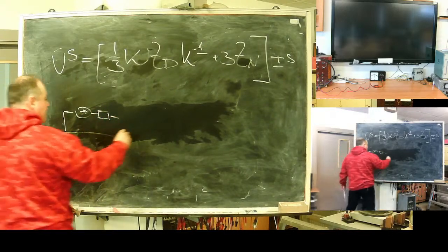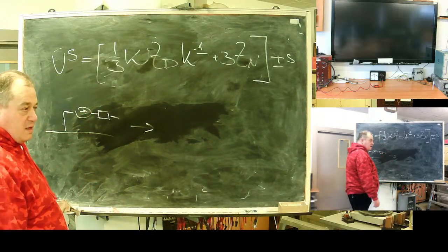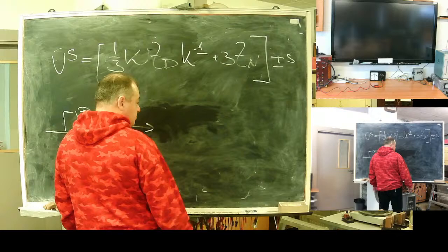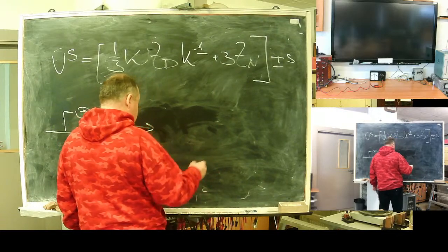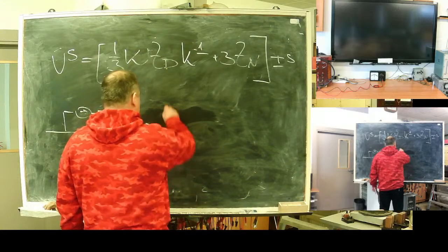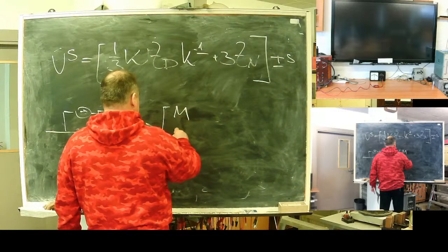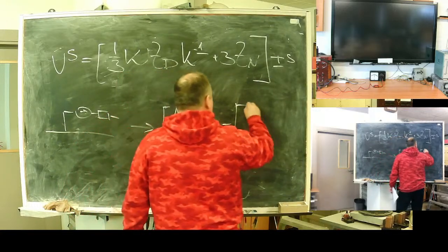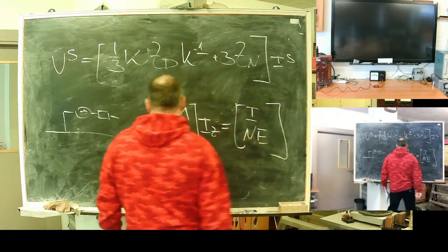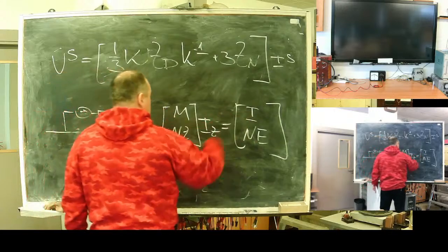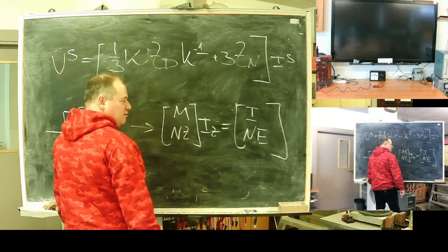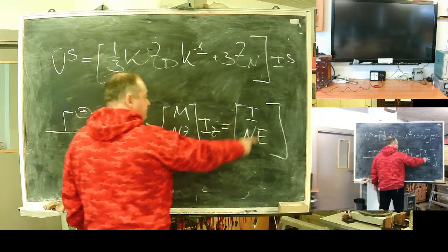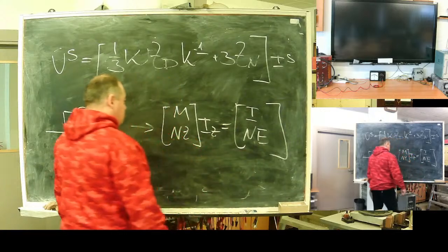Any real schematic can be represented in matrix form as a kind of equation system, starting from, let's say, Kirchhoff equations. First, Kirchhoff's current law, Kirchhoff's voltage law: matrix of nodes and branches, matrix of branch contours, resistance, branch currents, current sources, voltage sources, or EMFs.